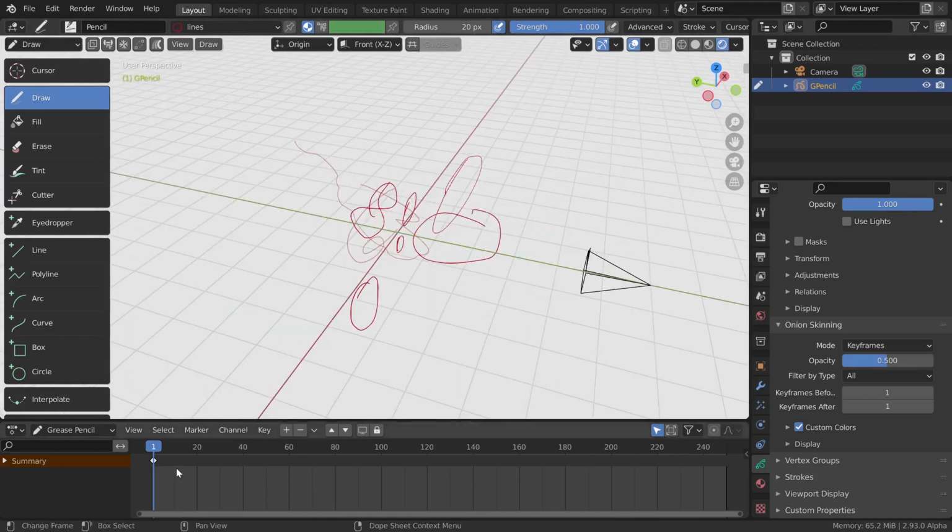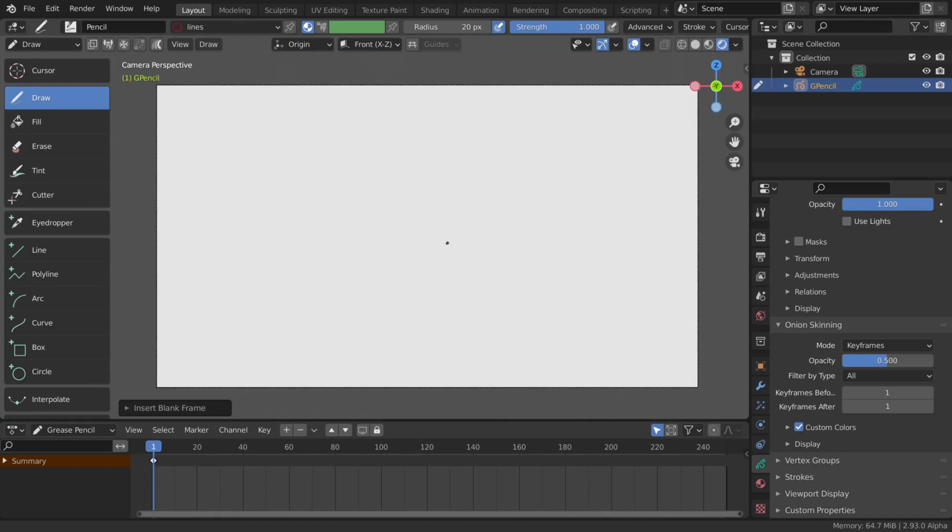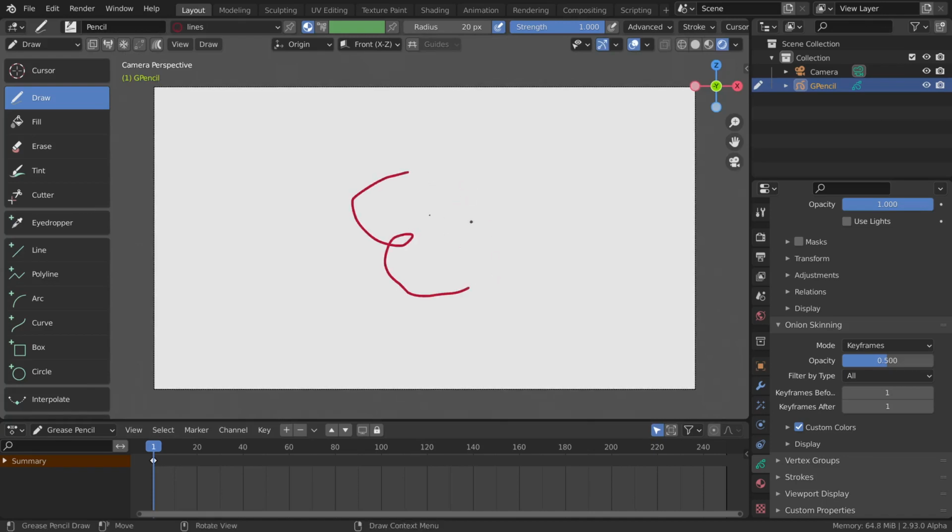There's several ways to do it, but I'm going to left click on this keyframe, press X to delete that keyframe. Then I'm going to use the shortcut key with the cursor in the main 3D view and go Shift I to add in a new keyframe. Then jump back into the camera, use the middle mouse wheel to scroll back into view, and we're all good to go.